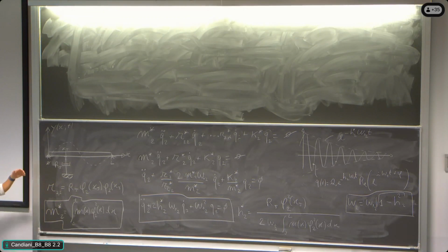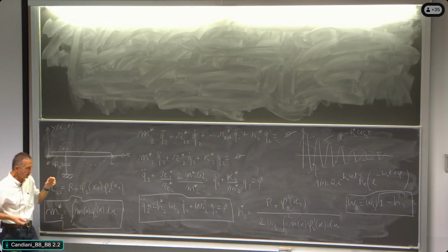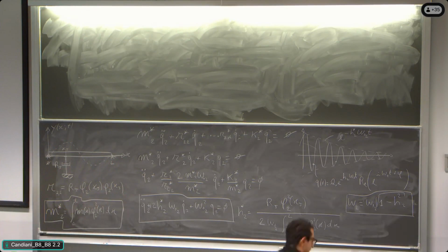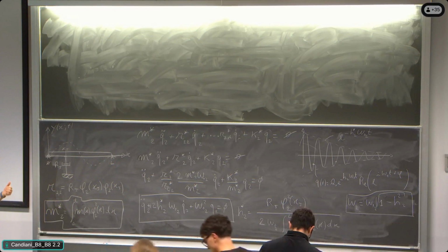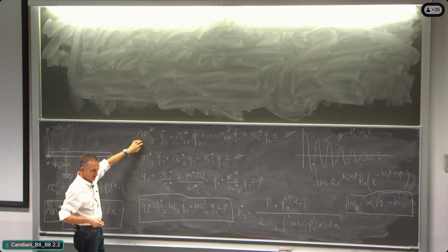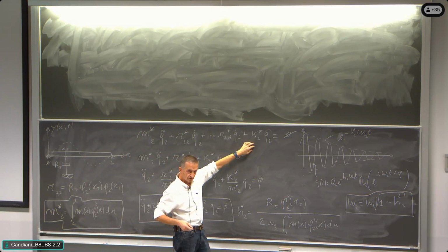So now I want to focus on the fact that I am using this damper. I am looking, for example, at the second mode of a beam, all right? And concerning this beam, I already made the study of the free motion, understanding which are the natural frequencies, which are the modal shapes, and which are the modal mass and modal stiffness, all right? So we know the quantity modal mass associated with mode 2. We know the quantity modal stiffness associated to the mode 2, all right?